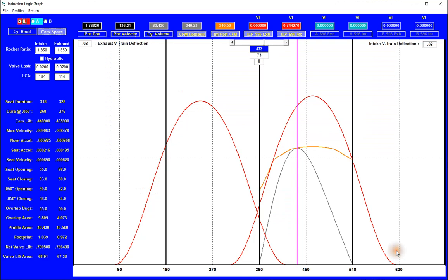Now, back to 7,400 RPM and the peak piston CFM demand. The port can now supply the demand, as raising the valve lift puts our 340 CFM at 768 thousandths valve lift. Let's take a look at what we have been talking about on our graph form. To save time, we have already designed and loaded the cam profiles. You can graph the cam lift, cam velocity, cam acceleration, and net valve lift. Net valve lift is graphed in red, the piston CFM demand is graphed in gray, and the intake port CFM supply is graphed in orange.